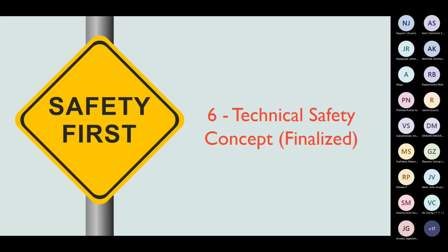And then we will be performing the FMEA analysis that will identify each and every component failure, whether we have safety mechanisms or not, what the diagnostic coverage is for each safety mechanism we added, and what the uncovered fault is, on both the single point fault metric side and the latent fault metric side. What is uncovered becomes the metric that is also used here to get the uncovered fit from the overall fit which we took from the reliability analysis for our entire product. So what is the safety related uncovered fit? First we consolidate all the fit rates based on the safety mechanisms we have, and then we come up with the final fit rate for the product.